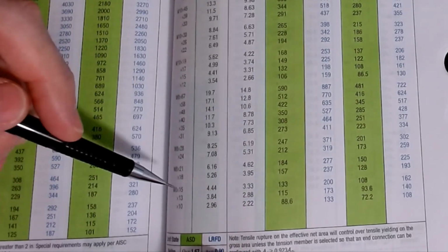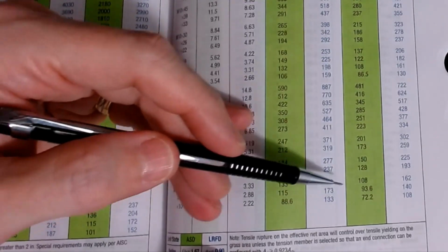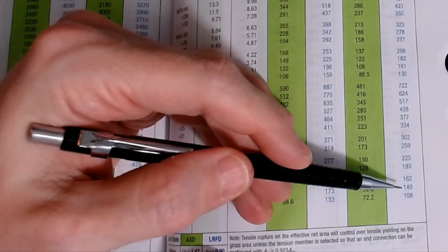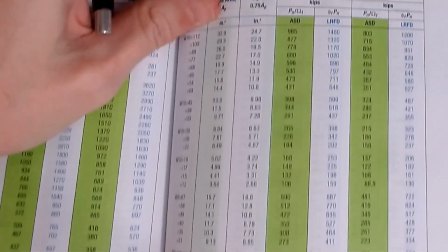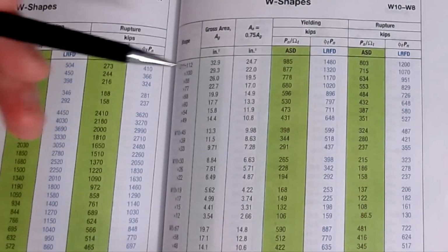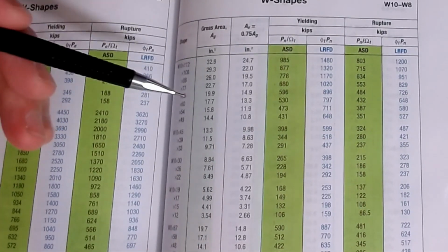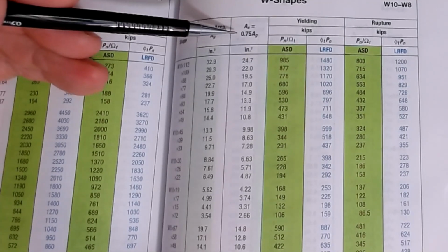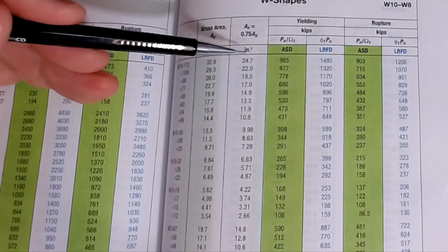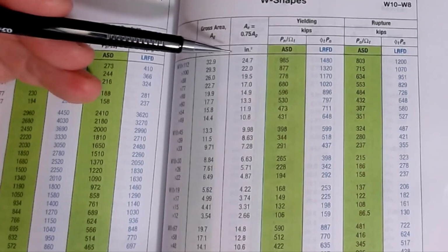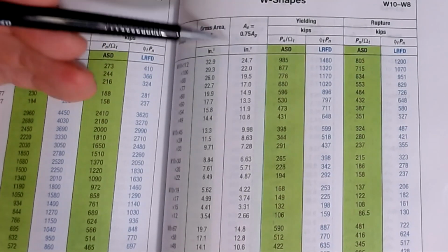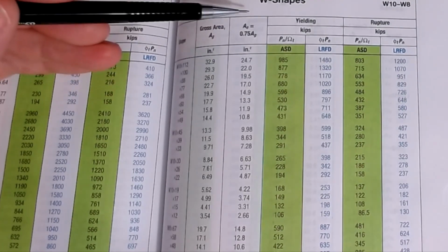Okay, now the problem that we have is that we know that over on the net fracture calculation, they're estimating net fracture capacity is 162. But what they've done, and what makes this table a little bit less useful than it could be, is that they're assuming the effective area is 0.75 times the gross area, that you're losing 25% of the gross area to the holes that are being popped in this thing. Okay, so you don't know this until you design the holes.